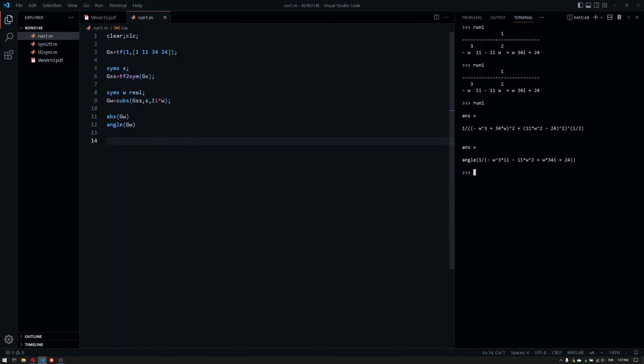But when we define the Bode plot, actually these two things are plotted and aligned on the x-axis by omega. So we have the x-axis omega, which is the common axis, and then we have the top plot, which is about the absolute value or the gain of the fraction or system or the expression itself, and then we're looking at the angle in the next one. So there are two plots on top of each other. The top one is the gain plot, the absolute value plot, and we have the phase plot or the angle plot, and they're aligned with omega.